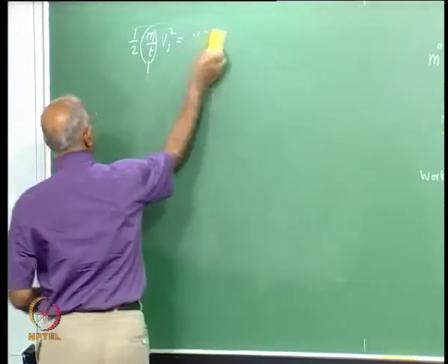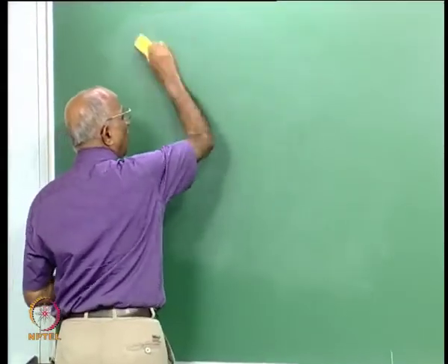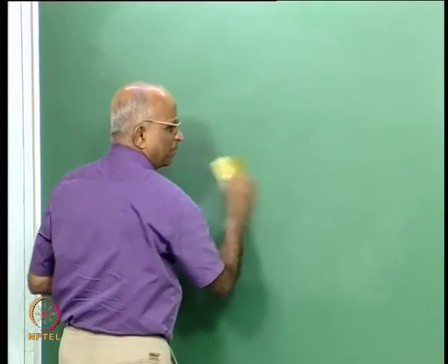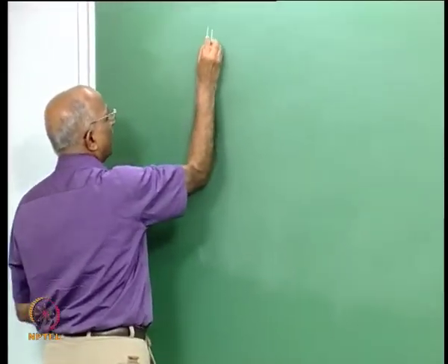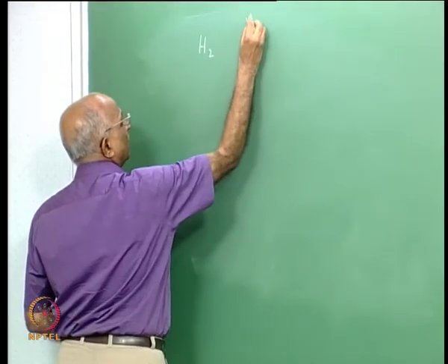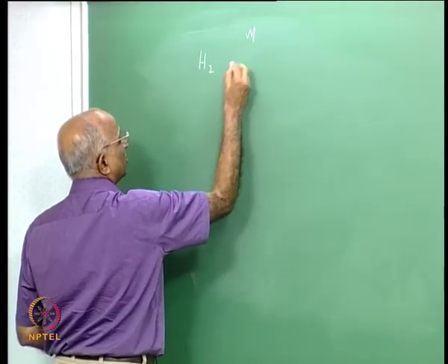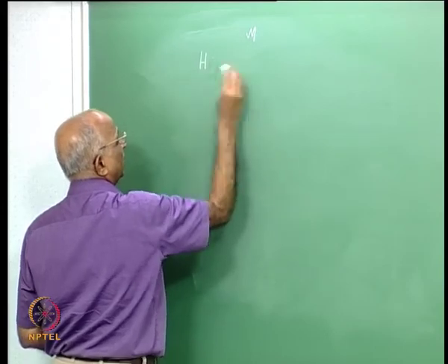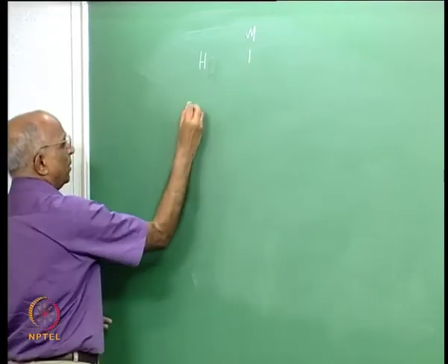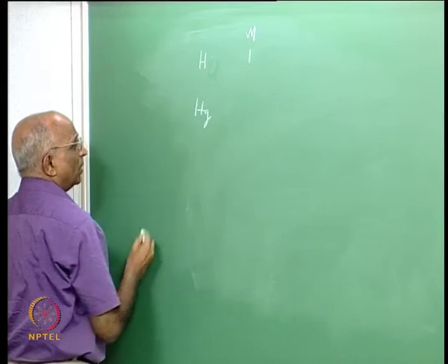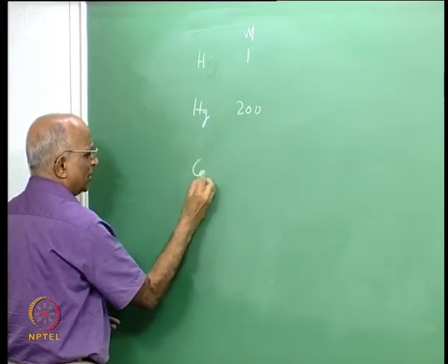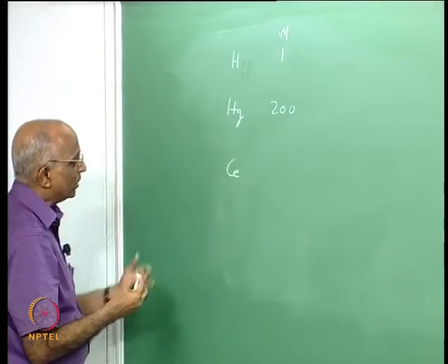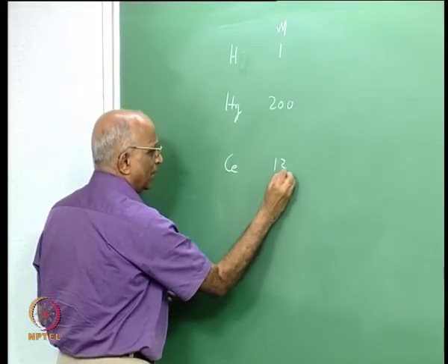Just like we said a propellant for chemical propulsion should have low molecular mass and high temperature, so also let us see, hydrogen has a molecular mass, compared to other substances, let us say hydrogen atom has 1. Maybe I take mercury, which has around 200. I take another substance, cesium, I will say why I am choosing this a little later, 133.